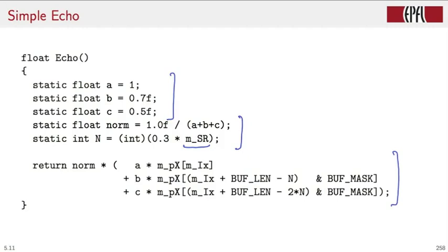The simple echo has two drawbacks with respect to a natural echo. The first one is that it has only a finite number of repetitions, whereas in a natural situation you would have a theoretically infinite number of back and forth reflections. The second drawback is that each repetition is just an exact replica of the original sound, simply scaled in amplitude, whereas the reflection process in a natural echo would introduce a low-pass characteristic in each reflection.